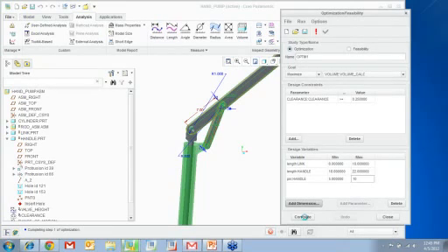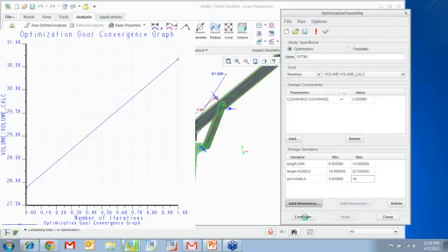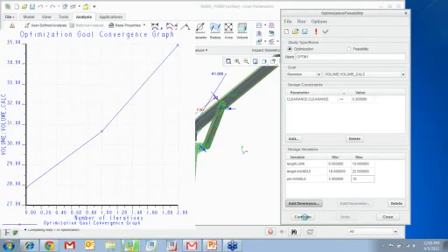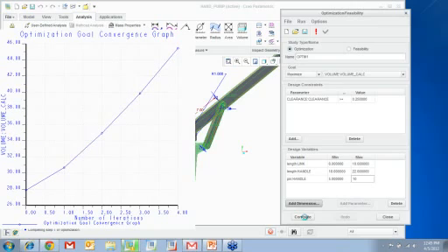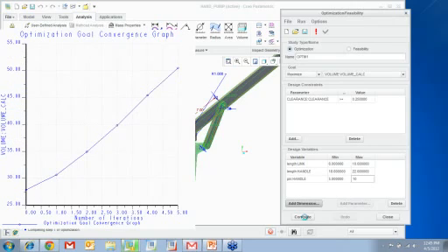So now it's going to try and change these design variables, maximize the volume, and also try to maintain the clearance value to be greater than or equal to 0.25. So here's an optimization graph. Now we need to make sure when we look at an optimization graph that it kind of asymptotically reaches a straight line, and then we know that, hey, it converged well. It's still running the analysis as we talk.